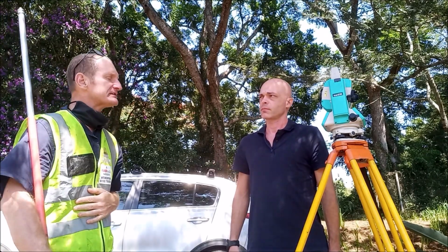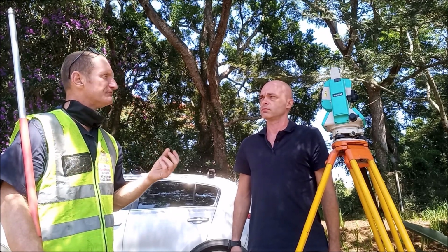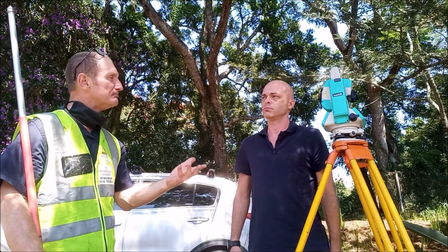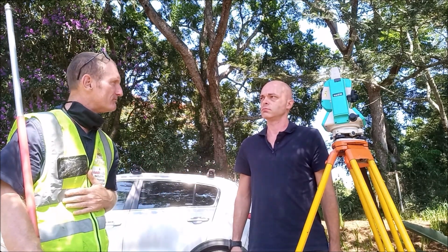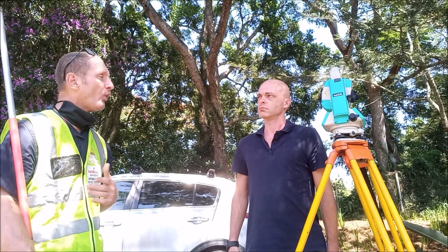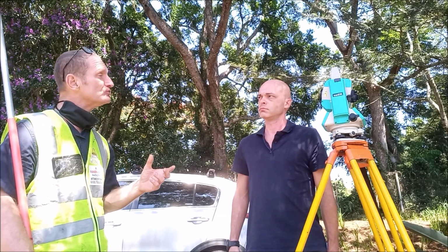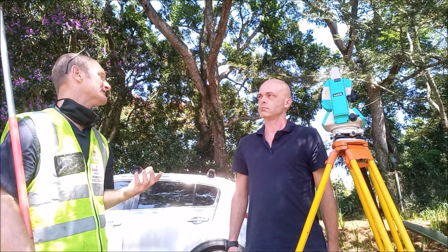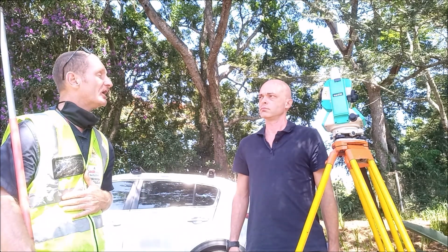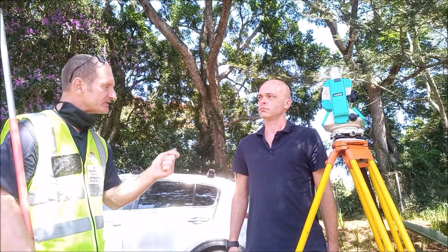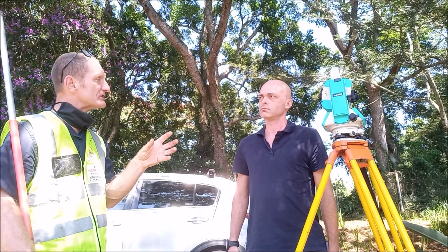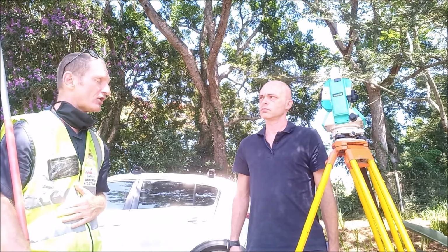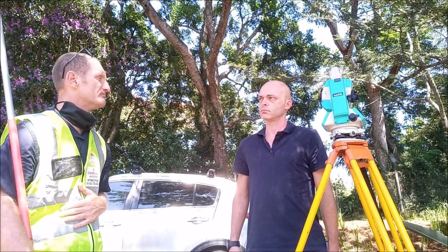Correct. So it may not necessarily be a measured, quantified value, but it may be a measurement in terms of just measuring an occupant being present or not. It's still a form of a measurement or a trigger or an activation, or it may actually be a measured value. For instance, you may have a particular sensor that could actually measure the weight of somebody seated in a seat, or as I mentioned earlier on, an actual steering angle. It could quite accurately measure the actual rotational degrees value of the steering. So there are many factors that are measured and very important.